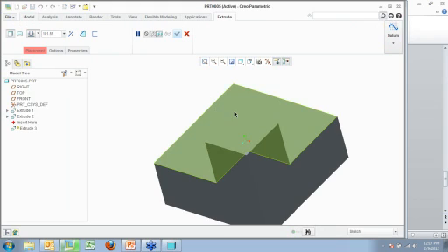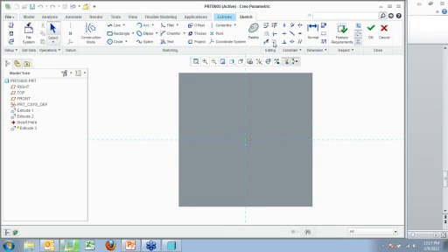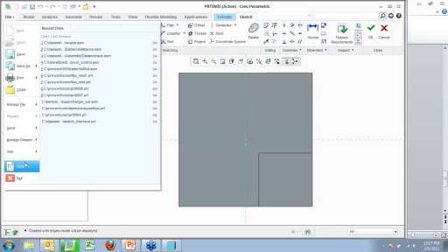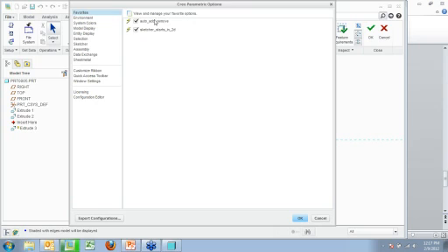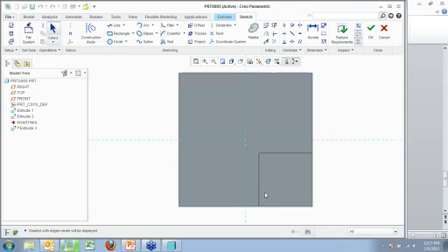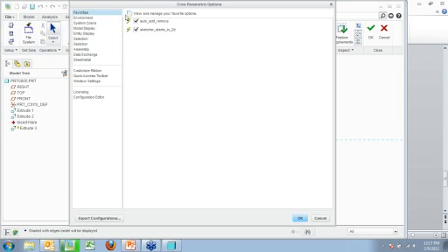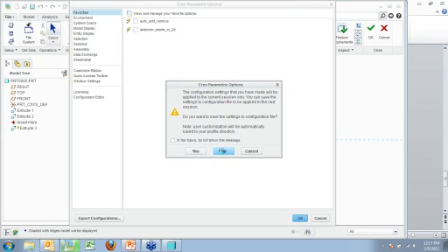So now I'm going to go in, extrude, select that face. Now it snaps back the way you would expect it to. I'm going to turn on shaded with edges so you guys can see my other feature there. So now let me show you the other feature that was on there. Go ahead and highlight that again. Options, favorites, auto add remove. That's off by default. So you go in, we'll turn it off by default. Set that back the way it was.